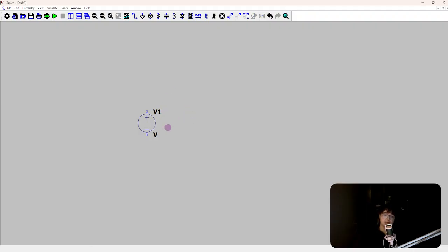All right, escape. So now, for the next part of our very complicated circuit, we're going to add a resistor. Boom, I just summoned it out of nowhere. How did I do that? Well, I used R for resistor. The resistor is found at the top here, but you can click R in order to get your resistor, right? So now we have a voltage source, and we have a resistor. And so we're going to connect these with wires. And we can get a wire up here, or we can click W. It's very nice, the letters that are associated with the keybinds.